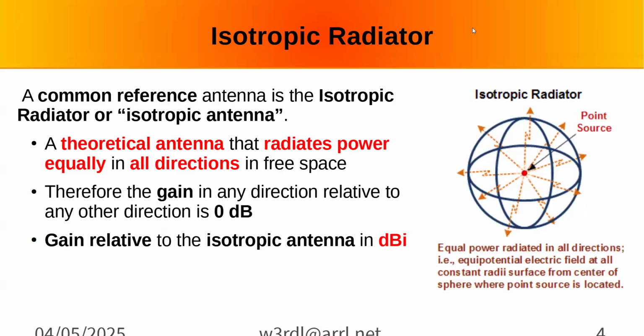But the total power on the surface of the radiation pattern is still going to be the same. If you put 100 watts in, there's 100 watts out, but if it's 100 watts in a very narrow lobe in one direction, then that's effectively more power than if you had an omnidirectional antenna. And that's all a directional antenna does: concentrate the power in a particular direction.